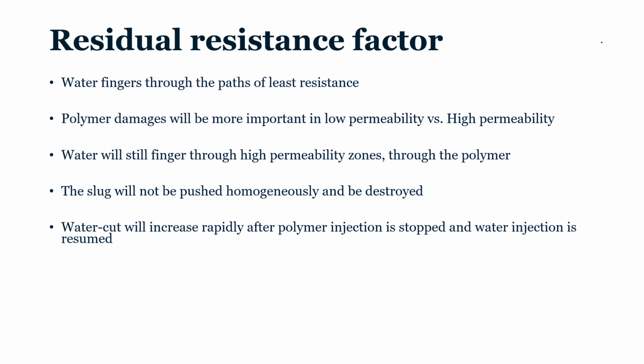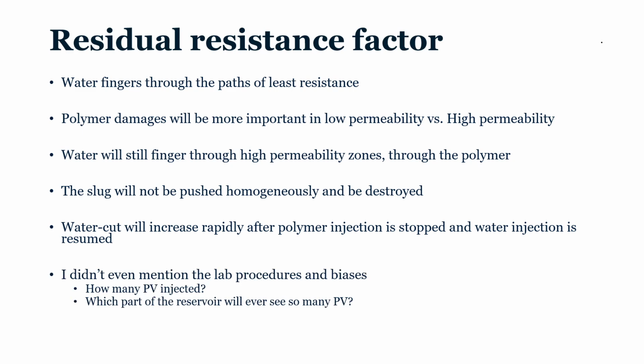So the slug will not be pushed, the water cut will increase rapidly once water breaks through the polymer slug. And not even mentioning that the value you might be getting from the lab and input in your simulation might vary depending on the procedure, how many pore volumes of water have been injected to calculate the value, etc. So it's complex already. So it's adding more complexity when you try to tweak slightly these input parameters.